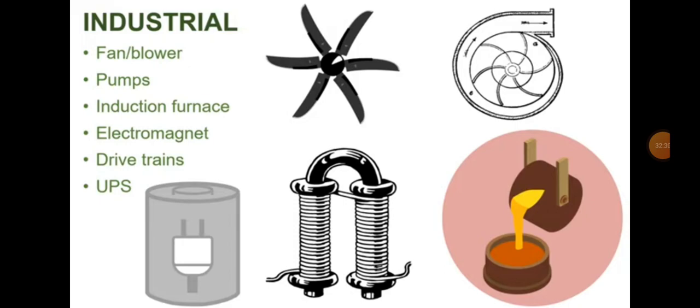Now, in case of furnaces, in earlier days, we were going for blast furnaces. Blast furnaces create pollution. Along with the pollution, the time constant required for heating up the blast furnace is also very large. Compared to that, induction furnaces, which use power electronic converters, have very small time constant, and the pollution can also be avoided with the help of induction furnace.